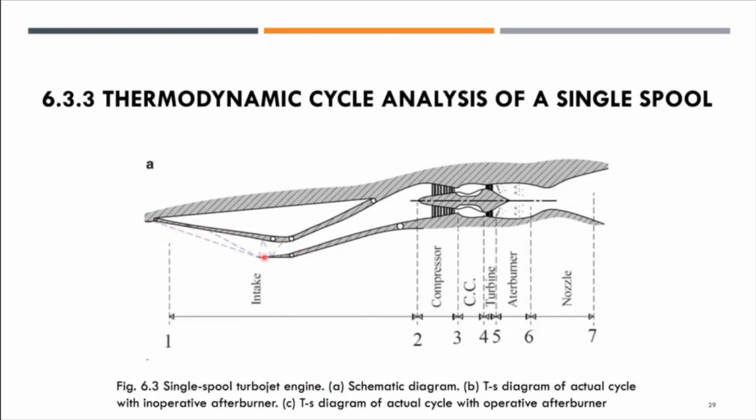As you can see here, this is not an ordinary type of turbojet engine. By looking at the type of intake or inlet, the aircraft is flying at a very high speed, and that's why we can see the dotted line and the shock wave generated based on the design. It is then followed by the compressor stages.